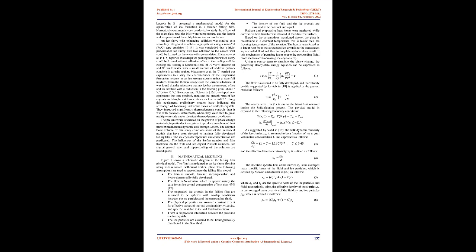produce an enhanced heat transfer medium in a dynamic cold storage system. The adopted finite volume of this study combines some of the numerical models that have been devoted to laminar fully developed falling films. The ice crystal temperature and concentration are predicted. The influences of the Stefan number and film thickness on the wall and ice crystal Nusselt numbers, ice crystal growth rate, and supercooling of the solution are investigated.